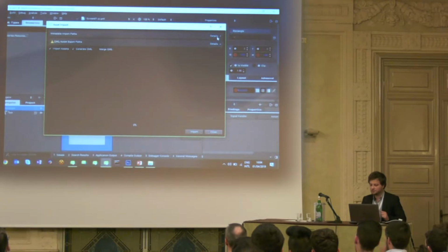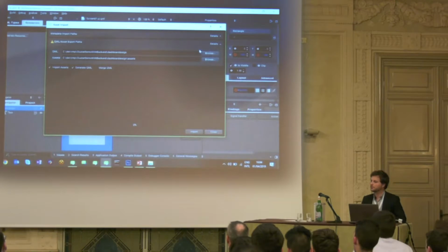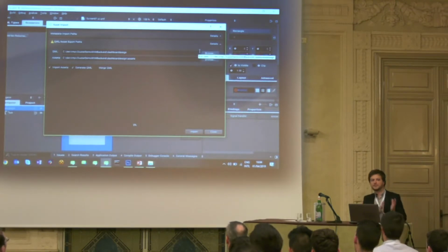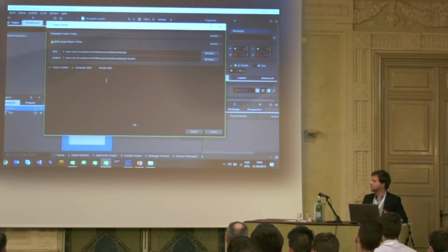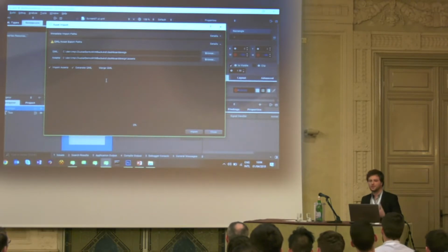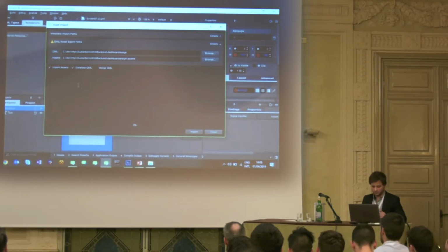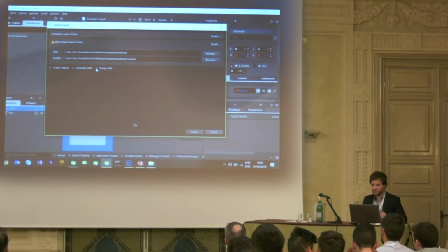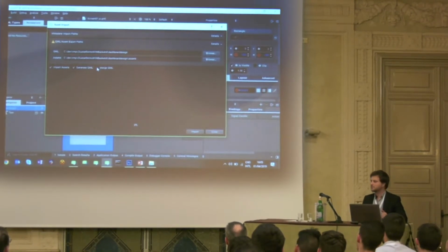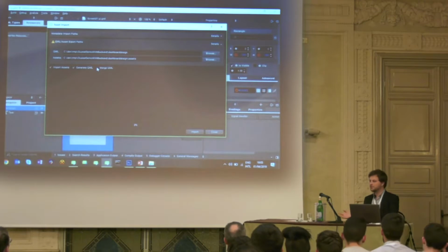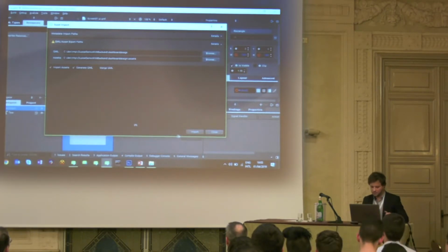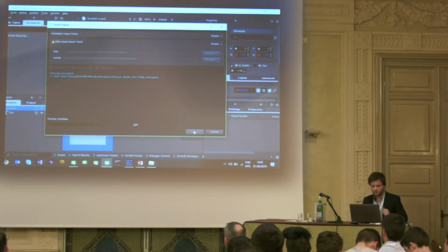And here you have a few options. You can tell it if you want to import only the QML part, only the image assets, or both. And in the case where you have an iterative approach and you're re-importing things over and over again, there's a merge functionality, you see here, so that you don't lose whatever you have done in the Design Studio. Right now, I do not need to merge because it's the first time I'm importing. So I'm going to do that.